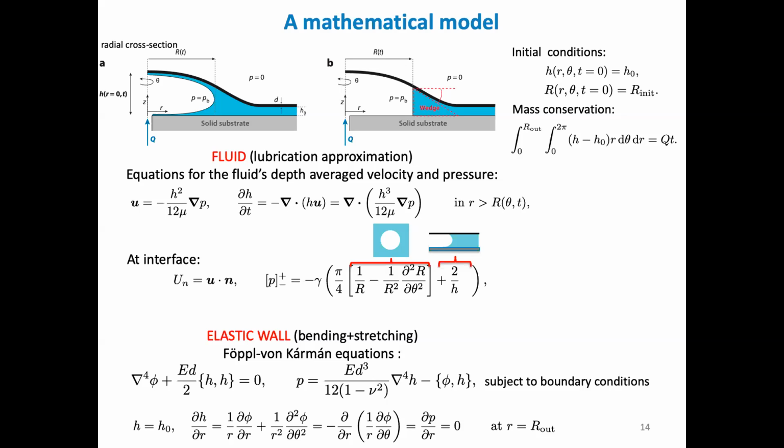So that pressure is the same pressure as in the fluid. The nonlinearities of these equations are contained within these curly brackets, which I haven't spelled out just to save some space, but you should be aware that these are nonlinear terms. We also have some boundary conditions that we need to solve. This problem needs to be closed by including mass conservation equations as well.